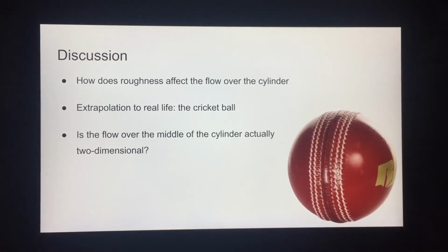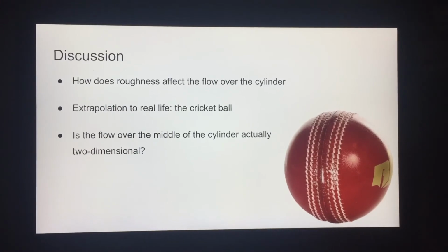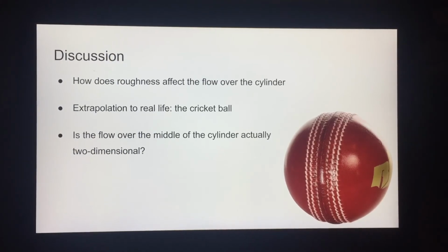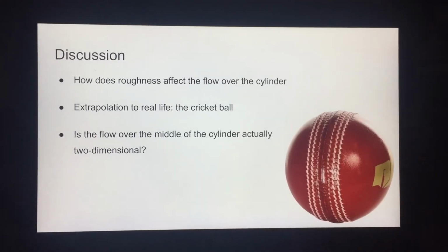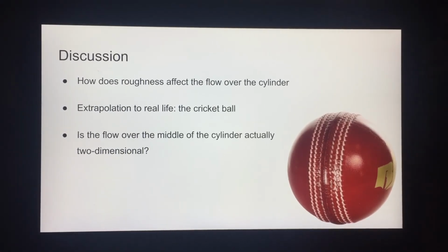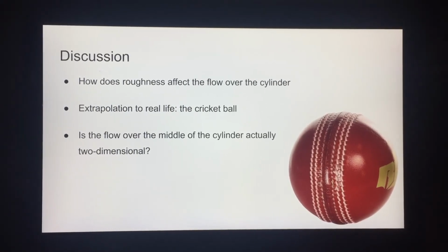Increasing the roughness of the cylinder also increases the coefficient of drag. Correlating this to the delay of the flow separation makes intuitive sense, due to the flow being able to stick to the surface for a longer duration, generating a higher drag force on the cylinder, thus augmenting the coefficient of drag.